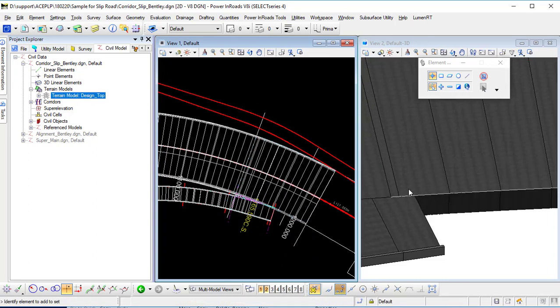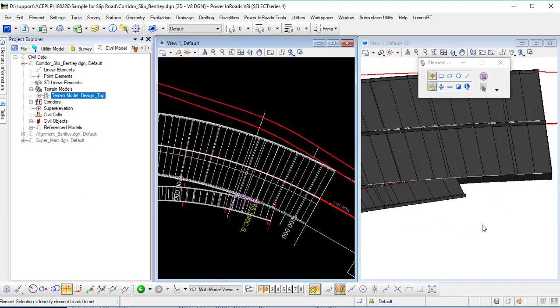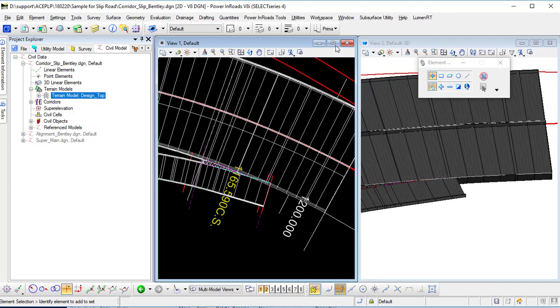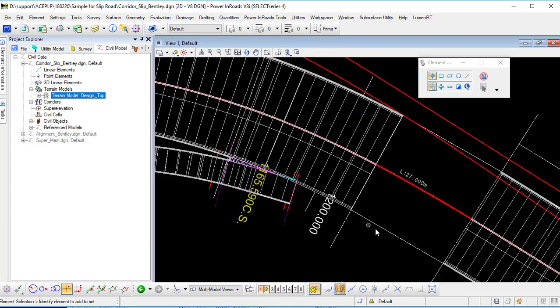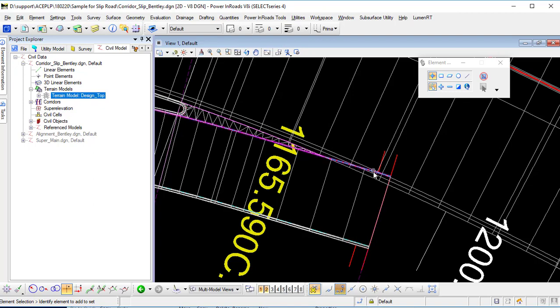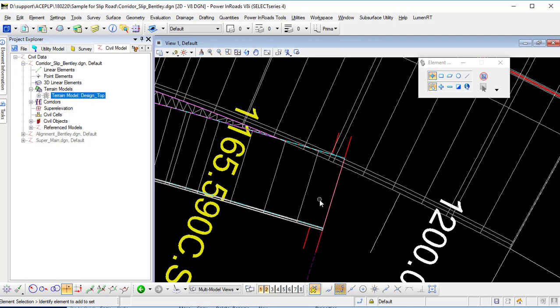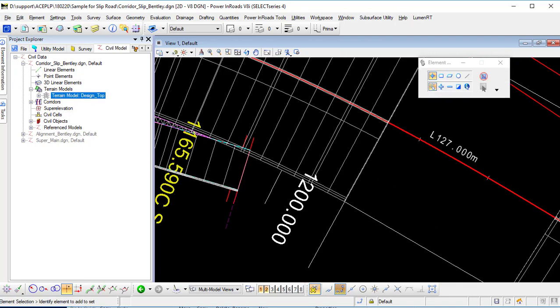Okay, however, you can have a look here. It seems that the alignment is not long enough for you to fit this way. So you had better give one more alignment here so that you can join the template here as well. So it means making the alignment longer so that it can join together. In this case, I recommend you check back the alignment design to see whether you have more alignments that continue to join it, or otherwise you create a new one here. So in this case, I just simply create a new one horizontally.